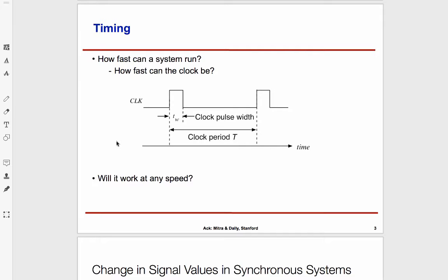There are also digital systems called multi-chronous systems. Chronos is time, so multi-chronous means multiple clocks. Instead of a single clock, they may have multiple clocks which are synchronized to each other and aligned, like one is a multiple of another, but different parts of the system operate at different rates. Again, we'll not worry about those. What we have is a single clock operating at some rate, and we don't care about the pulse width, we'll only care about the period.